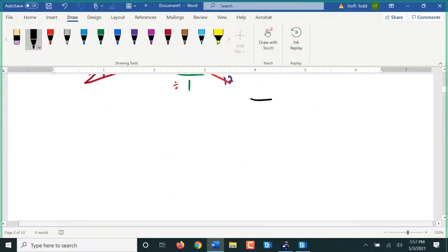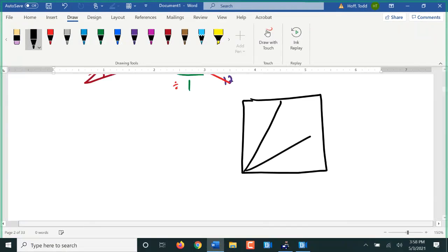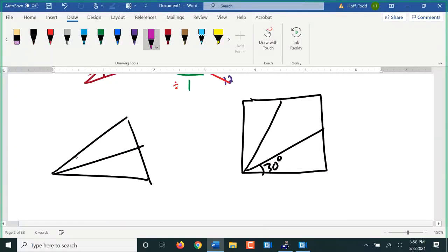So can we get away with a 3-step winder? Well, let's try. This would be 30 degrees here now, right? So this is going to be half of 30 or 15 degrees. This is still 12 inches, right? It's the right angle. I'll find this dimension, I'll call it A for now.